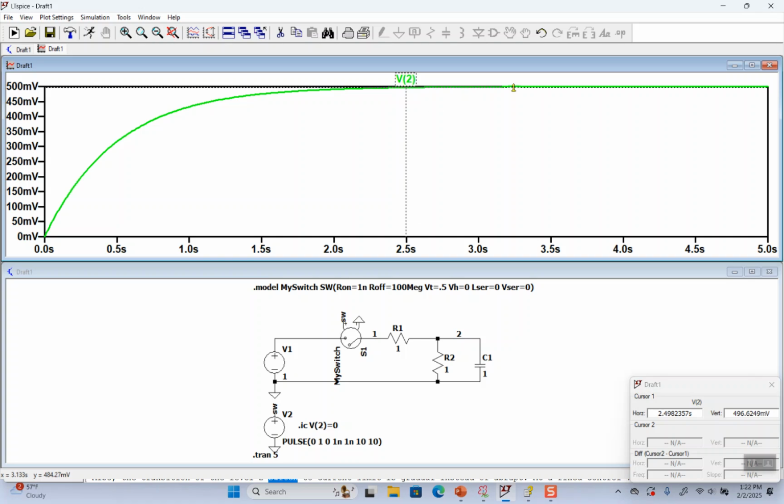So it's sometimes a trick. Just the way this simulation goes, it goes to 5. You might be thinking that's 5 tau. But in fact, 5 tau doesn't go exactly to where it's ultimately ended. It's just close enough, and then we all agree that 5 tau is what we're doing. So it's actually half, right? It's not 1 ohm times 1 farad times 5, right? It's actually half.